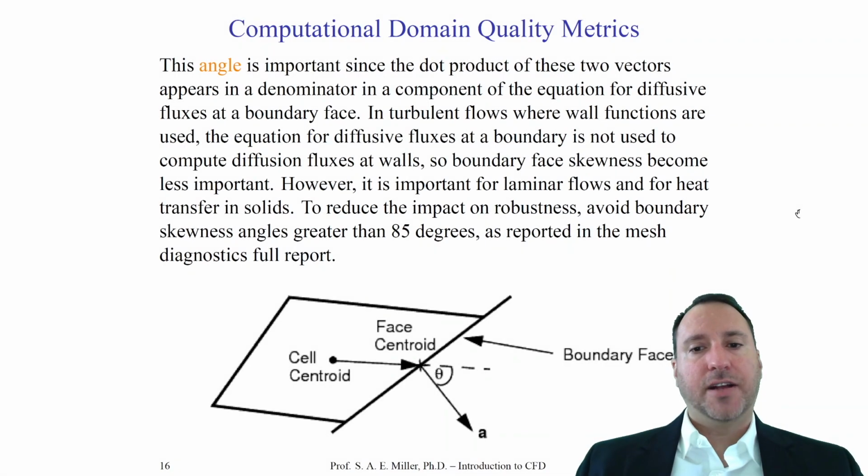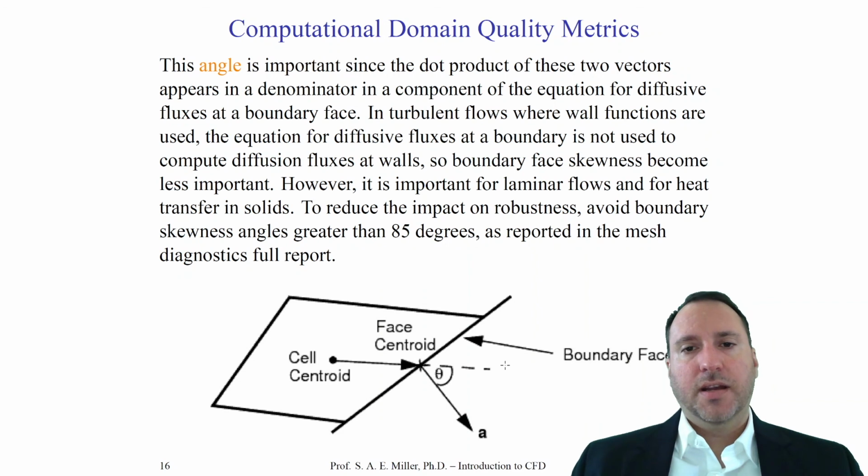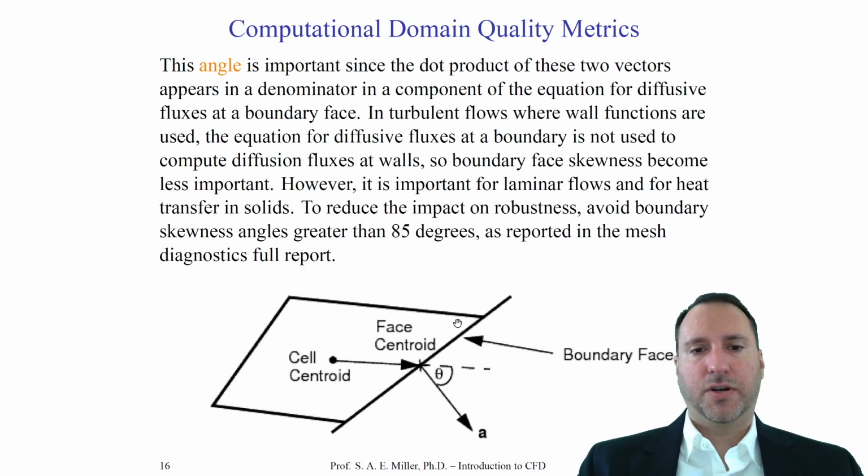Another one is the angle relative to boundary face. Here in the lower figure, we might have a wall along our vehicle, and there might be some cell center or grid point connectivity to the wall grid point that makes a large angle relative to the wall. We call this the wall angle, typically. Now, if the wall angle is very small, like 10 degrees, like in this corner, well, not here, it would actually be the other angle to the left. In theta, you would want to be near 0.